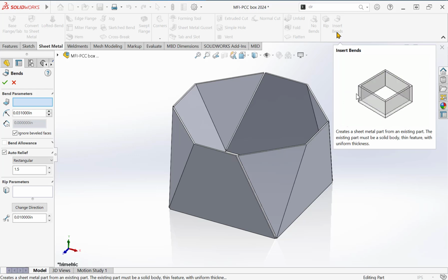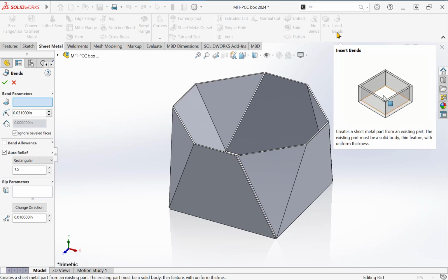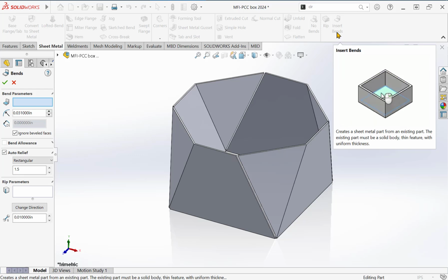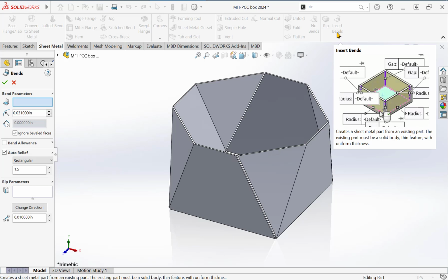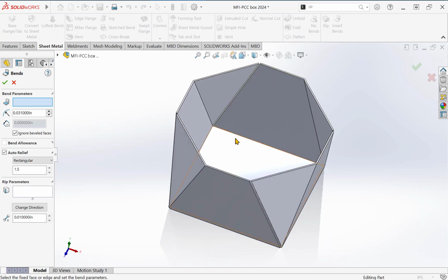The first thing, turn everything to sheet metal. The second thing, try to flatten this and make it a flat pattern, basically. That's what we're going to cut. And then it will refold it, and we should see a completed sheet metal part folded up when we're done. The first box that it wants is the fixed face or edge. That's going to be the bottom. It could be the inside bottom or the outside bottom, doesn't matter, but it's going to be the square bottom of our box.